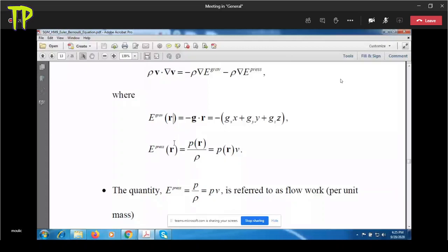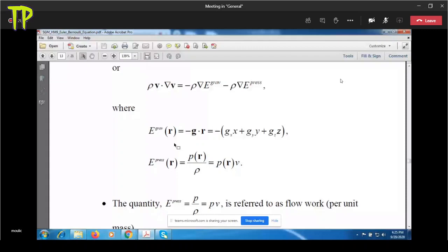If you look at a simple example, let us say you have an ideal gas in a cylinder with a piston. Suppose the gas expands, so volume changes, and it's a quasi-static process. Then the work done will be the integral of PdV. Now that will depend on how P varies with V. It's a path function. If you have an isothermal process, then PV will be RT, or PV will be constant. If it's reversible adiabatic or isentropic, then PV to the power gamma will be constant. Then the work done will be different.